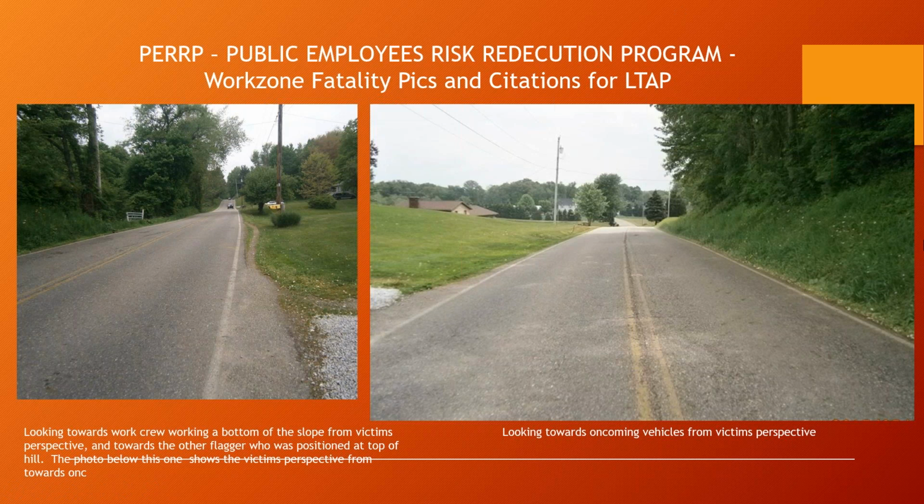So this really makes me sad, because it wouldn't have taken much to set up the work zone and alert the motorists, especially in situations where you have sight distance restrictions. A sight distance restriction with high-speed traffic is where you have to take the extra precaution, and that's where you would use the options that are listed in the flagging operation, like the extra sign and things like that.